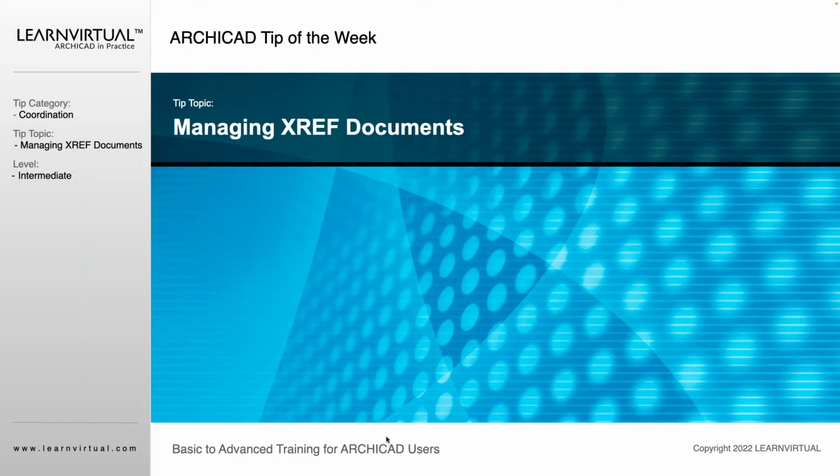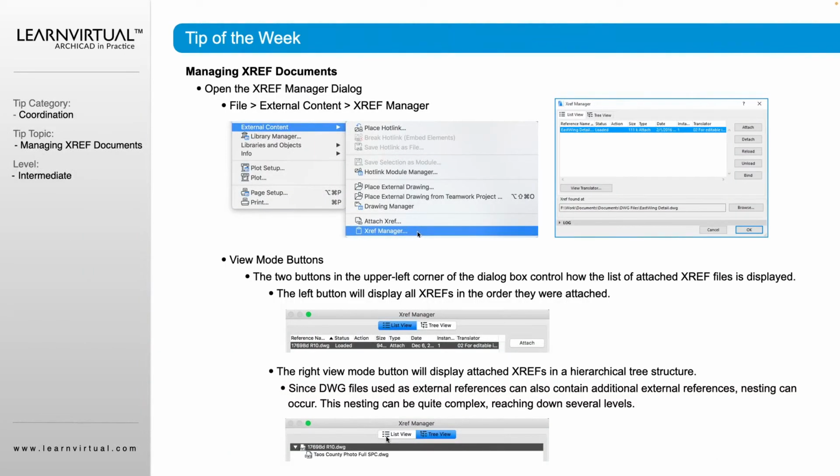All right, our tip of the week, we're going to talk about how to manage our XREF documents. So we had talked a little bit on how to attach those XREF documents in our presentation before. You go to File, External Content, and at the very bottom we have Attach and Manager.